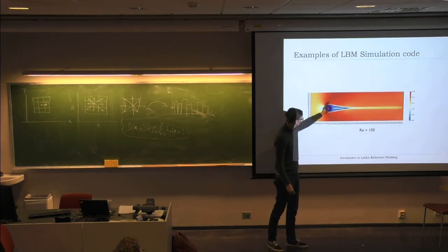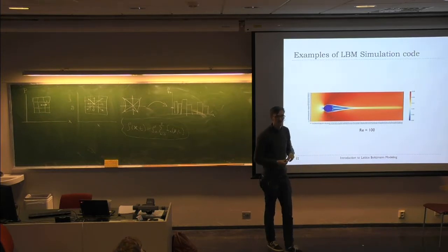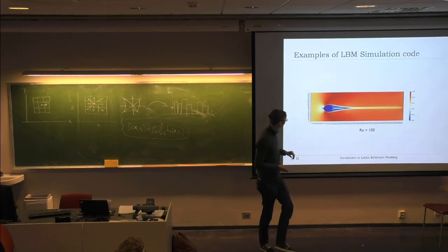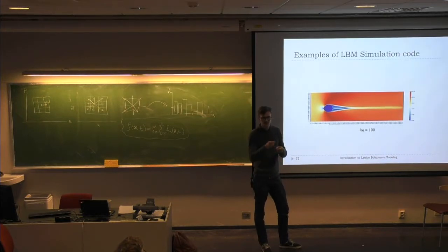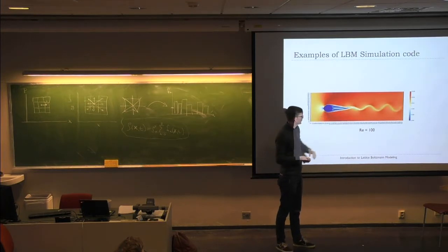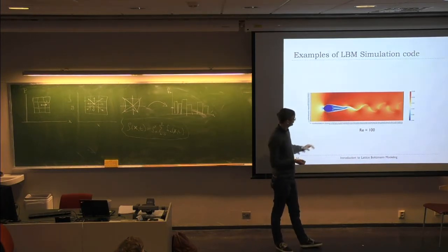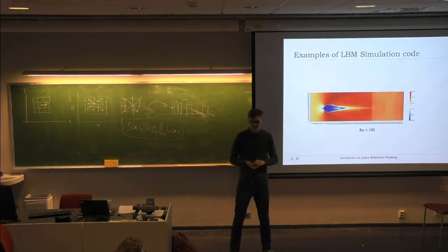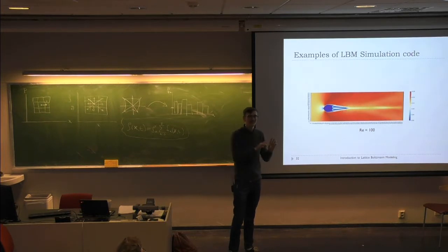Here's the cylinder, the pressures, or the density. Oh, sorry, the velocity field. You guys had fluid dynamics earlier. So you basically have no flow in the nose here, and so you have the velocity for each of the nodes, the macroscopic velocity that I talked about, and what you see behind here is actually an artifact of turbulence. So you get these eddies that I showed in the plot in the beginning.